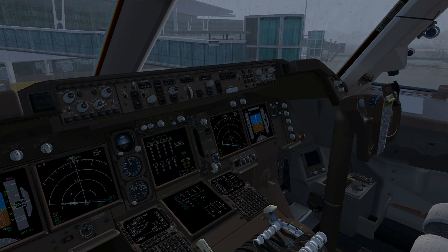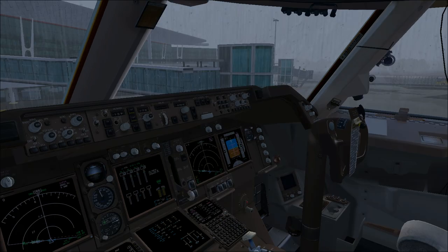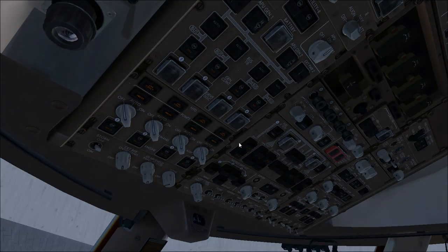We have the clearance to pressurize the hydraulic system, so we go to the hydraulic panel up here. As I said, we have to pressurize system 4 first to prevent any mixing of fluid, so we set it on AUX. You can see now park brake has hydraulic pressure. System fault lights are out and checked, and the press lights stay illuminated. This is important: hydraulic pressure pumps 1, 2 and 3 must be set on.